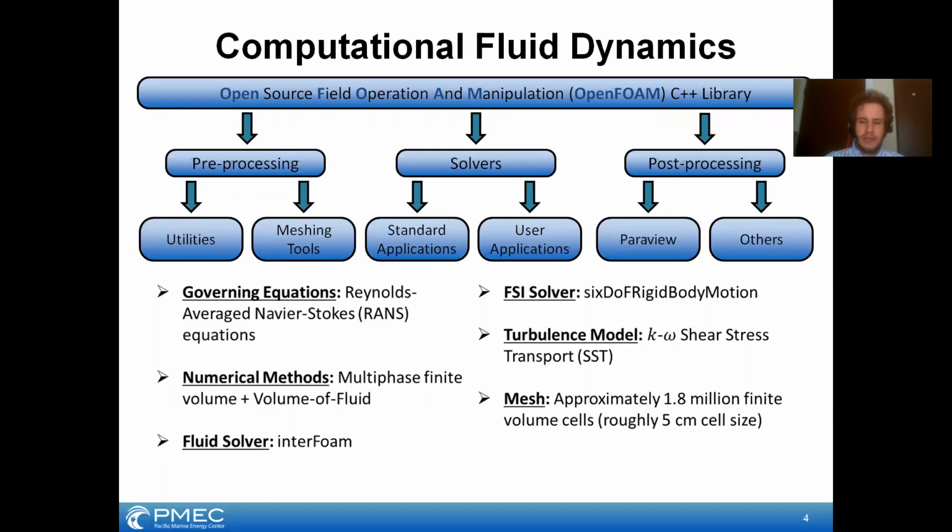For turbulence modeling, we've got Menter's k-omega SST shear stress transport model that he developed in the early 90s, and it's very good for bluff body flows where you might have separation around the sharp corners of the body. And so this is why this was selected. It's a very robust turbulence model if you're only going to go as far as using a 2-equation one.